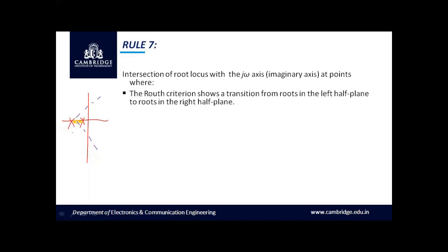Let us take an example with two poles in the negative real axis, and it is in the region of root locus. And let us assume that we have two asymptotes. So these are the locations of the poles exactly when k is equal to 0. When k increases, there will be a moment when the branches will be trying to emerge from this point, and both will intersect at one particular point, as it is valid for minimum one breakaway point with respect to this condition, and it will break away,